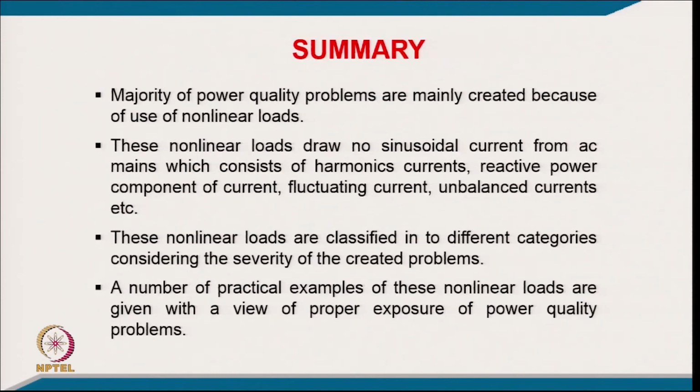Well, we would like to summarize now what we did in this chapter on nonlinear loads. The majority of the power quality problems are mainly created because of the use of nonlinear loads. These nonlinear loads draw non-sinusoidal current from the AC mains, which consists of harmonic current, reactive power component of current, fluctuating current, and unbalanced current, and these nonlinear loads are classified into different categories considering the severity of the power quality problems created, and a number of practical examples of these nonlinear loads are given with a view to proper exposure of power quality problems.